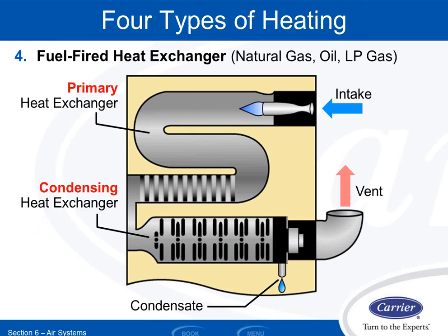Robert types in, why does the gas heat in a furnace coil serpentine downwards instead of up? Right. So in this example that I was talking about, I have an upflow situation, which means my air is where my red dot is down here. Hopefully you guys can see that red dot. My airflow is coming up through the heat exchanger this way and then being delivered to my space.